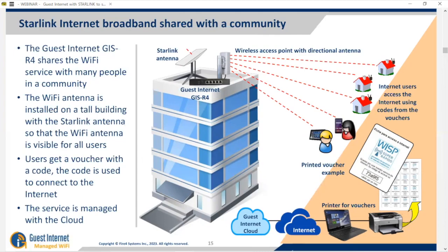With Wi-Fi, it's very important that the person wanting to connect to the antenna has visibility of that antenna, because the Wi-Fi signal can be blocked by buildings, by trees. And the same for the Starlink antenna. That must have visibility of the sky, which is horizon to horizon, 180 degrees, in order to ensure that it can track satellites as they move across the sky.